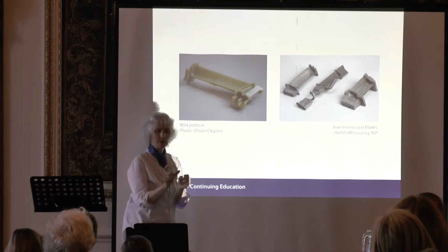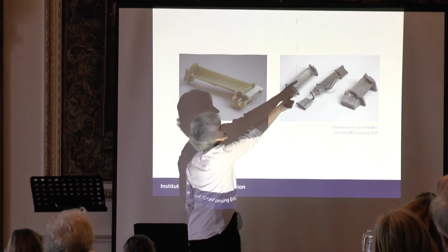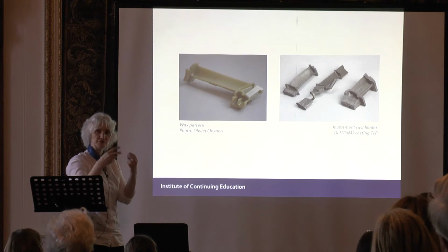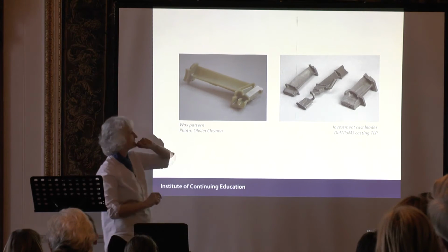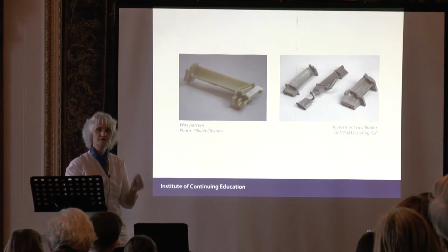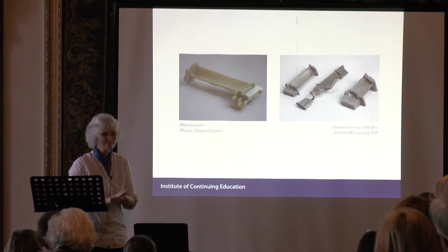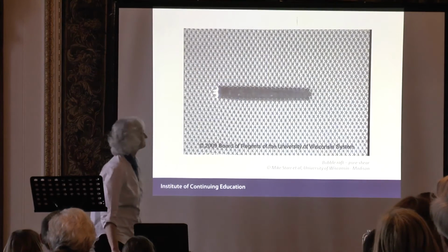And these turbine blades are typically a few inches long. So here, inside this blade, every atom is arranged quilt-like, tile-like, in exactly the right place through the whole of that volume. So that's good. We've got rid of all our boundaries. Is that good enough? Not really, because something else happens.